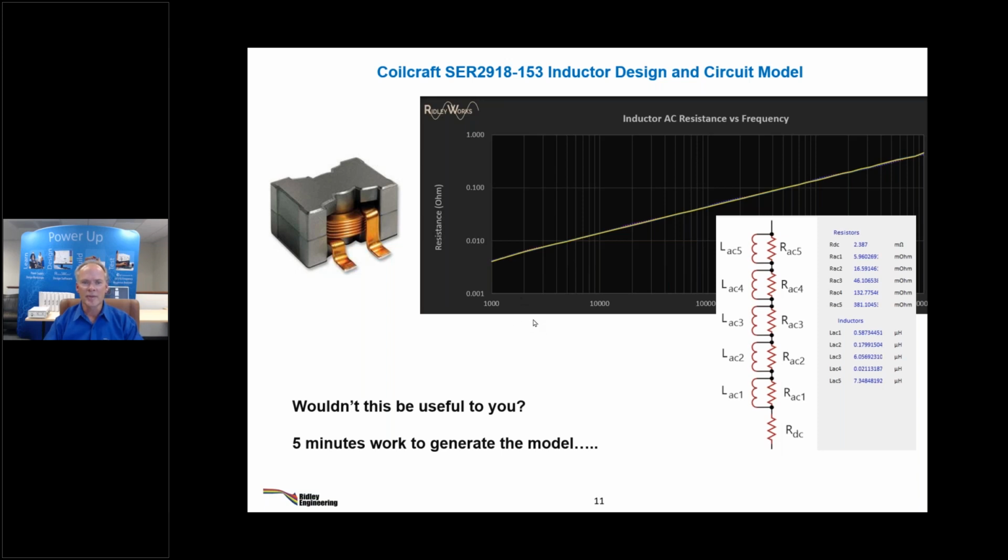Should I be zoomed out to capture many steady state switching cycles? Well, yeah, but we don't want to zoom all the way out because we've got startup. So you want to capture one complete cycle. I do 10. If you can zoom exactly on one and catch the edges, then it's going to be the same as if you caught 10 exactly on the edges. And then if you caught 100, you wouldn't have to worry about whether you captured the edges or not.